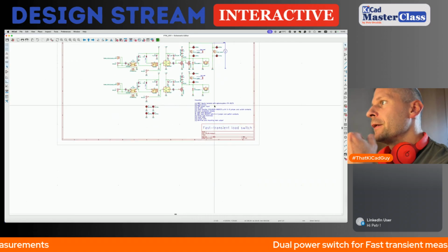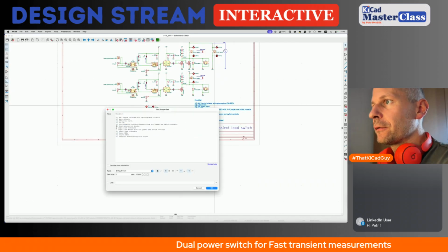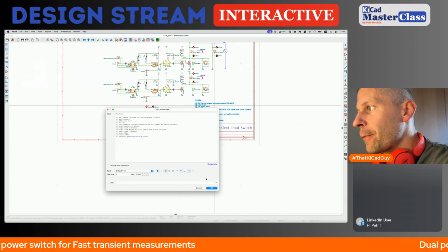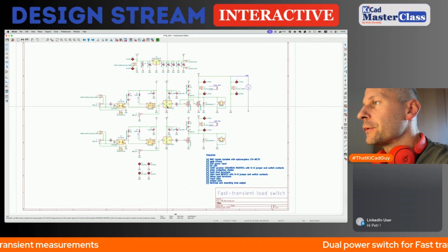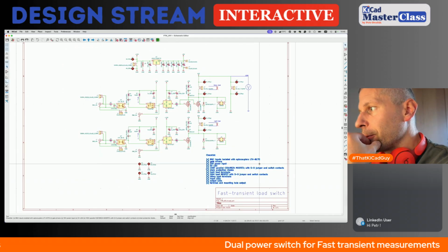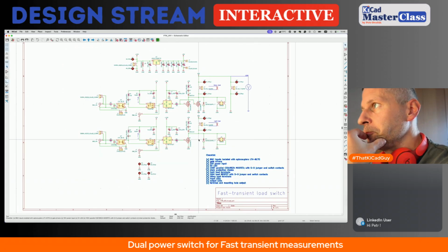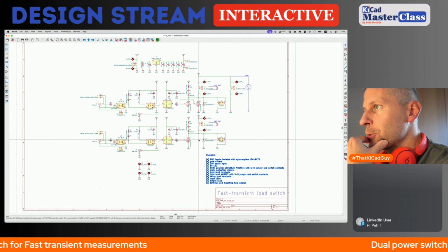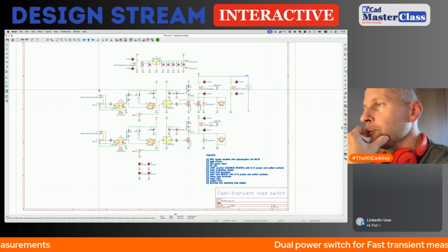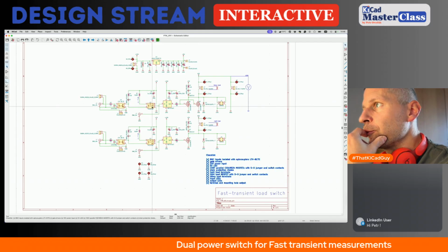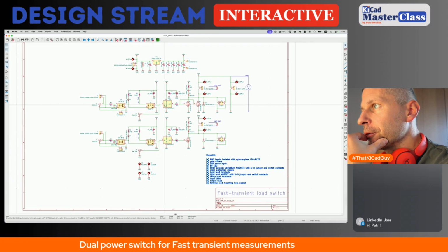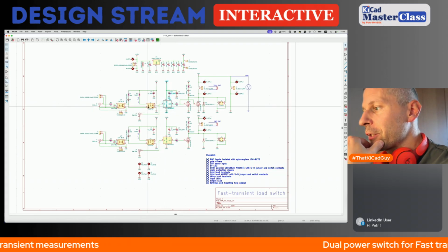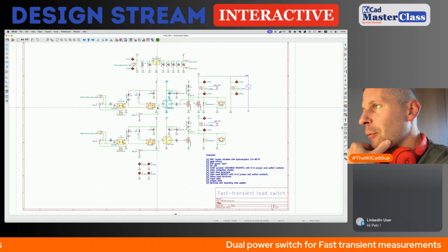Yes. So let's check the checklist. Light load terminals we have, light load MOSFET we have. Okay, so this can be our simple fast transient load switch. Yeah, I can't see any issue right now. Input, LED, optocoupler for the gate driver, ground is connected, so there is no isolation function, there is only driving capability of its output.